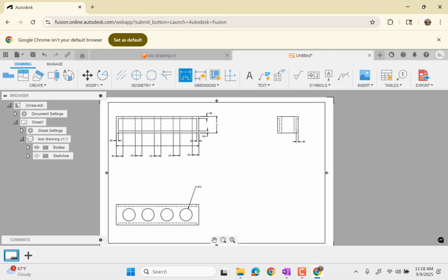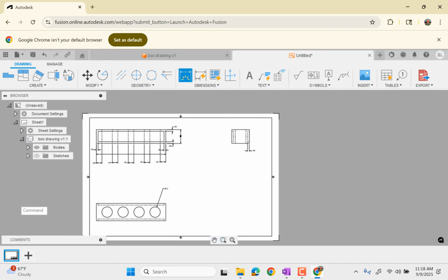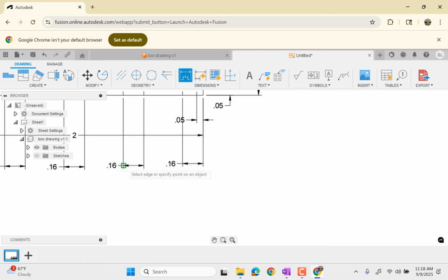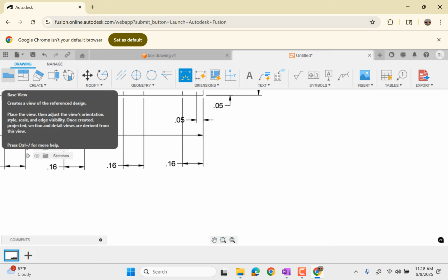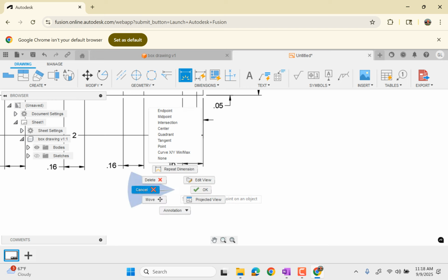How do you make them bigger? On my trackpad, if I use two fingers and scroll up or down, it makes the sketches bigger and smaller. Oh, how do I drag them into place? No, how do you make them bigger? I suppose they're not bigger, but you can change the sizes of the dimensions. Double click on the base drawing again. It'll pull up that little window and you can change the scale again. Oh, I don't know about the dimensions. There is a way to change the font size of the dimensions.